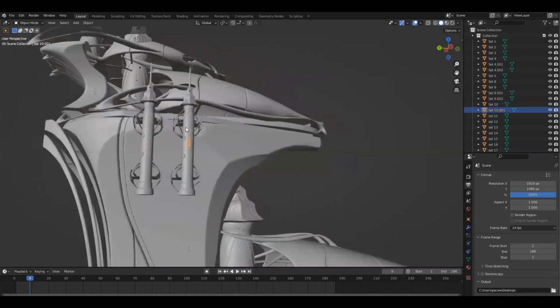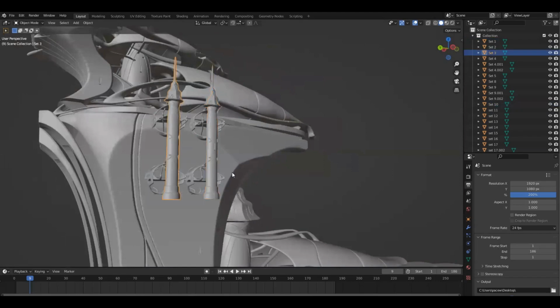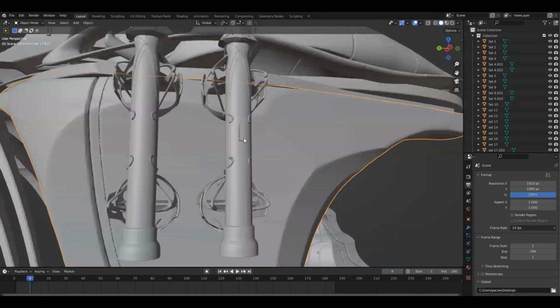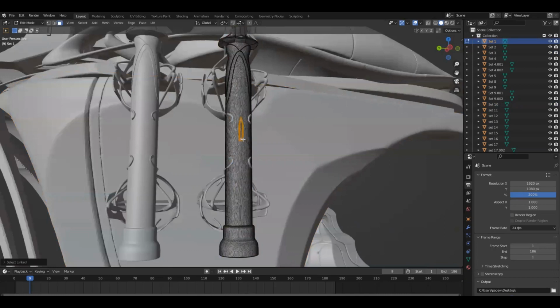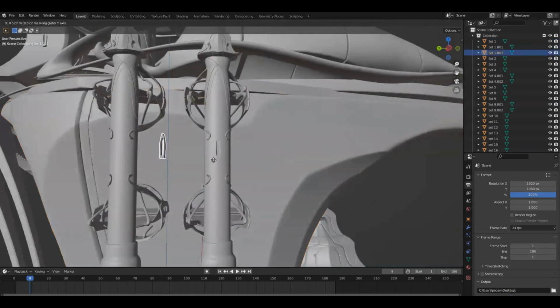And we'll probably add some more windows in a second too. Looks like this one didn't get a window, so let's go ahead and add one right now. So let's select that. We'll grab that window, P to separate again, and I'll just Shift D over here.